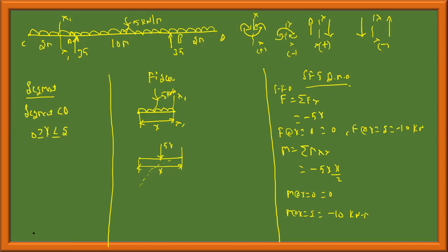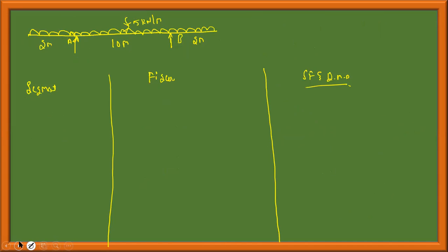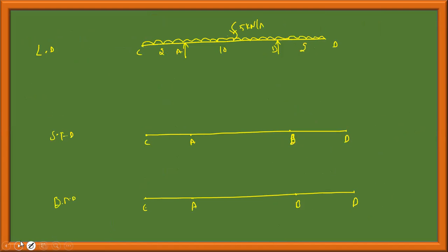Okay. This is constant load. Therefore, shear force is linear. Bending moment is parabolic or quadratic. You should look how I plot the curve. I can't go to the previous slide always. Shear force at x equal to 0 is 0. At x equal to 2 it is minus 10. I'll be plotting this. This is linear.